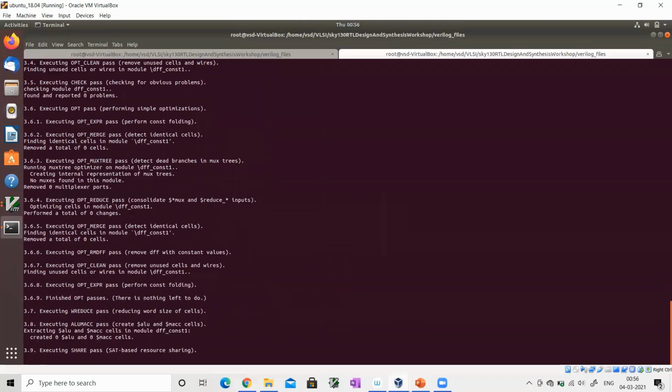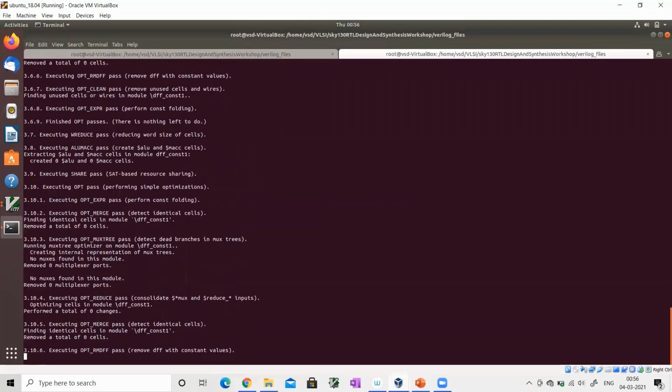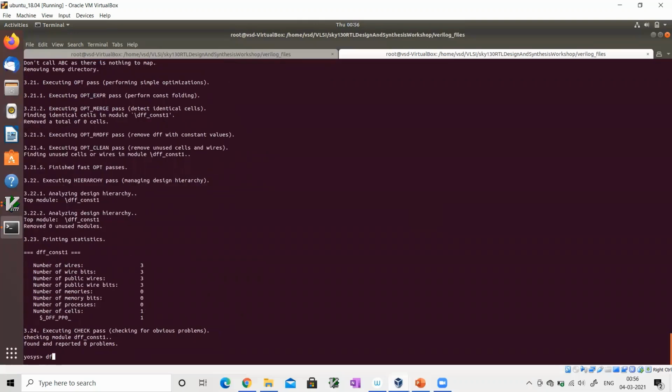const1. Now here we need to do one extra step, because so far in the design we have been seeing only combinational circuits, but here since there's a DFF, we need to do something called dfflibmap. Again we have to point to the library. This is for mapping the DFF, because sometimes libraries may be written in such a way that for sequential circuits you have separate libraries, and for combinational circuits you have separate libraries, or you may have special flops in certain cases. So dfflibmap is the command which tells the synthesizer, for sequential circuits, mainly DFFs and latches, what library it has to pick.